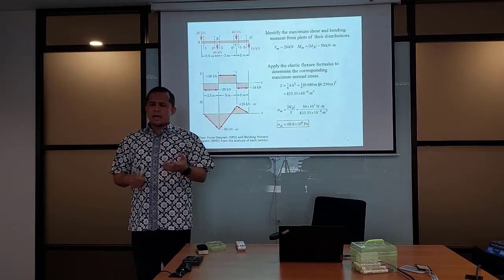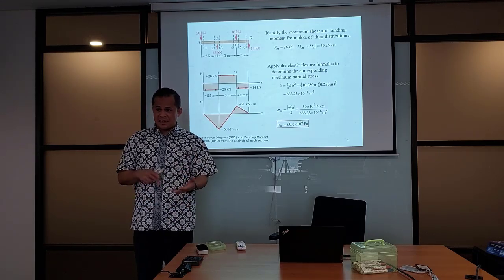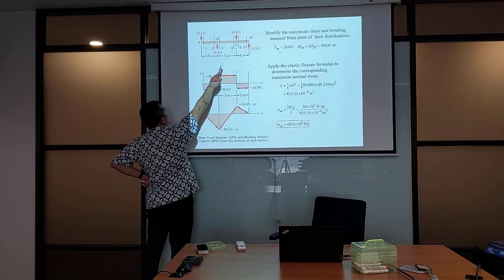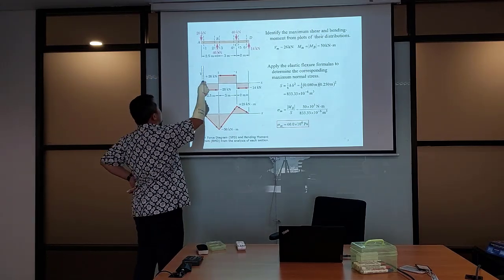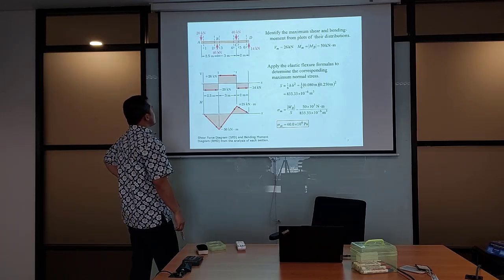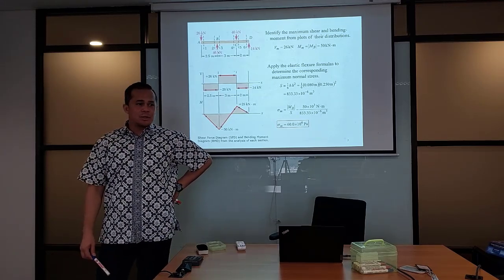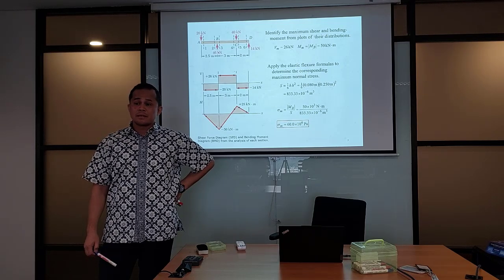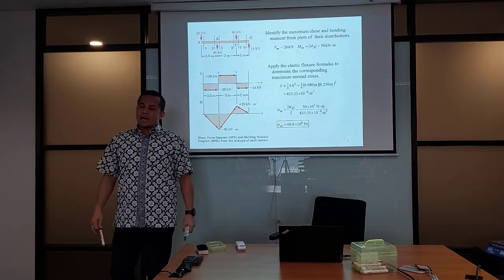Now look at here. Applied load is the gradient of the SFD. The SFD itself is the gradient of the BMD. So you see now the beam is under concentrated loads of 20 kN, 46 kN, 40 and 14. Now, the 20 kN, if I ask you, is it a constant or a function? Constant at this particular location. Then after A, nothing.